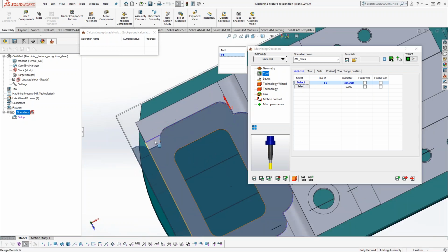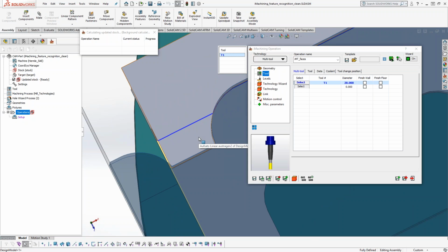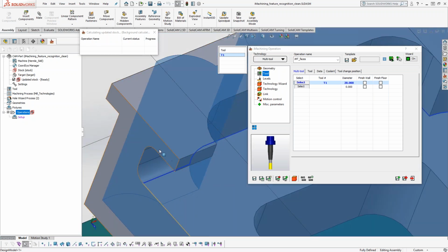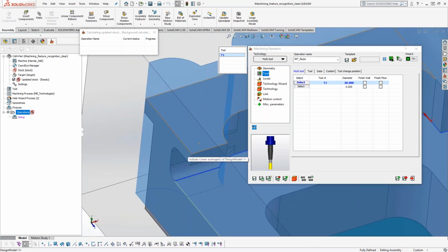we will protect against the target. So in this case, you can see we have this undercut. We have this little ledge that's hanging over. In something like a normal feature recognition, you might click this face, and it would just gouge this overhang and cut it away, and then you would have to deal with it. And with the machinable feature recognition that we do, we say, okay, we can't machine that portion of the geometry because it would gouge it.